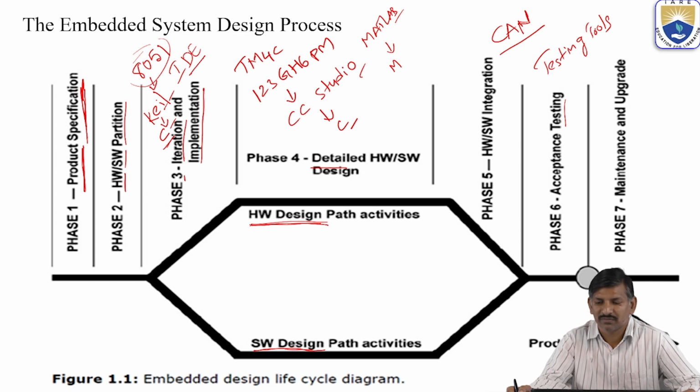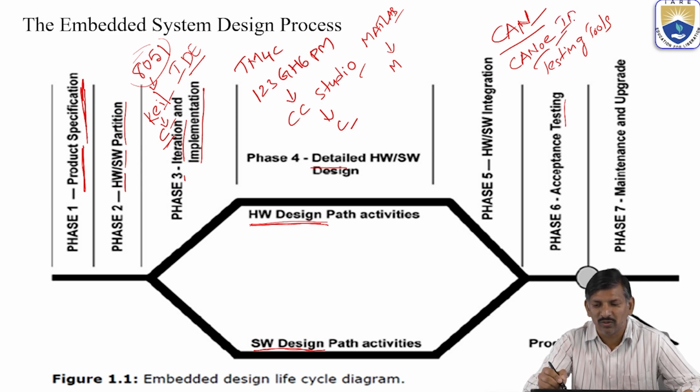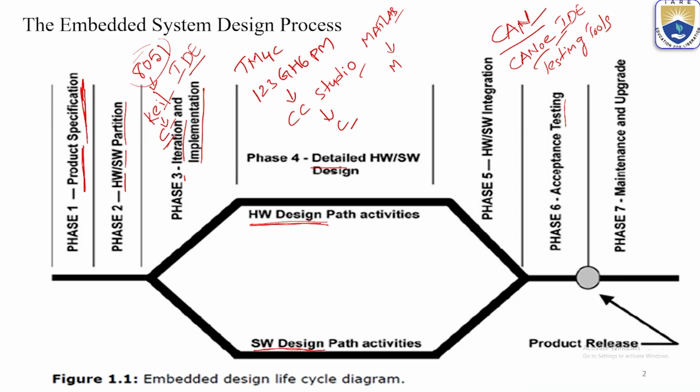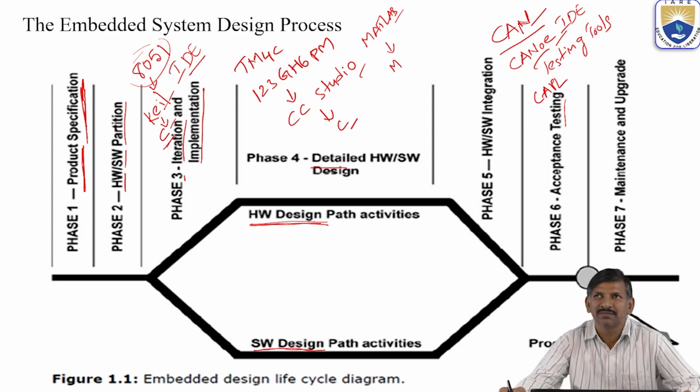We need to check. For testing the CAN bus, the tool is CANoe. For verifying the response in the CAN cable, I am using the CANoe IDE tool. IDE means Integrated Development Environment. In this, I am using CAPL script, CAN Access Programming Language. By writing different test cases, I am verifying and testing the CAN bus response.